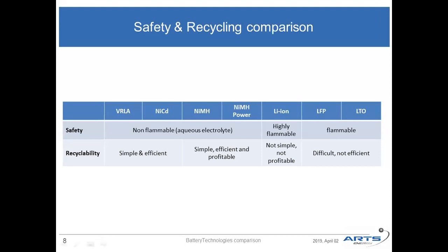But the difference compared to lead acid and nickel cadmium is that the recycling of nickel metal hydride is highly profitable, because in nickel metal hydride you have a significant amount of nickel, cobalt, rare earth, and so the value of the waste is very interesting. You have approximately 40% of nickel in weight in a nickel metal hydride battery.